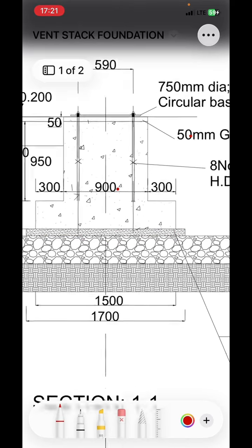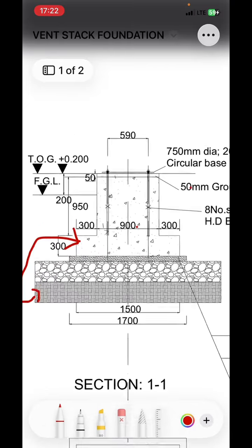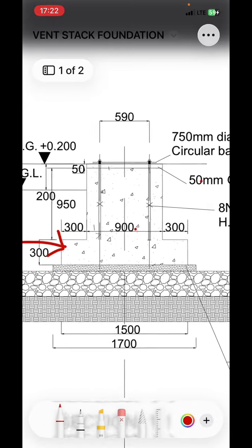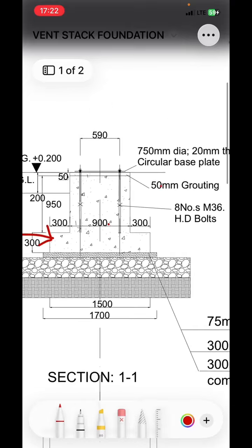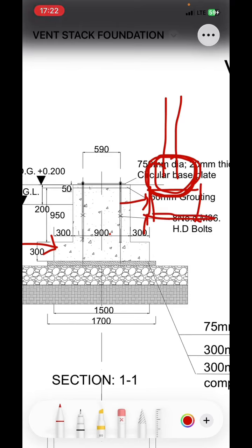So this footer, for me, and the soil being compacted have a similar purpose when it comes to weight. Remember I talked about the compacted soil preventing the iron steel or this entire base from sinking into the ground. So this footer helps to distribute the weight of the iron steel pipe. Remember, this is an iron steel pipe, and it has a metal plate just below it, and that metal plate is sitting on this thing called the pedestal. I'm coming there. And that pedestal is sitting on something that is a bit wider called the footer.